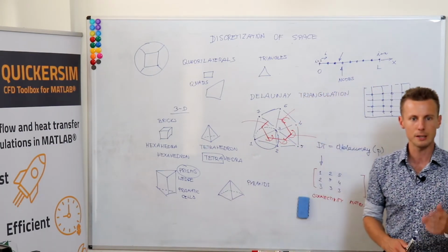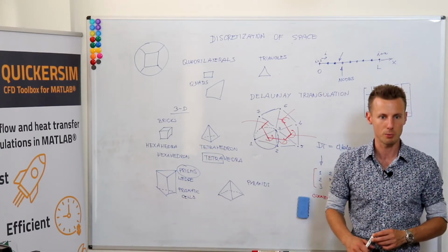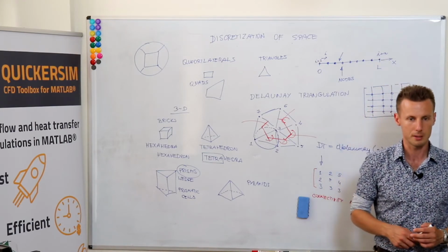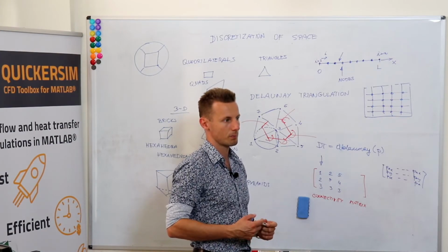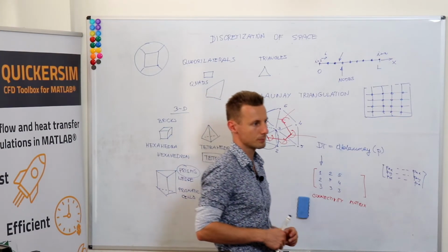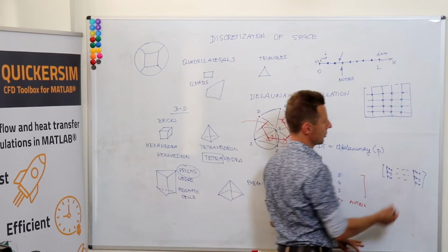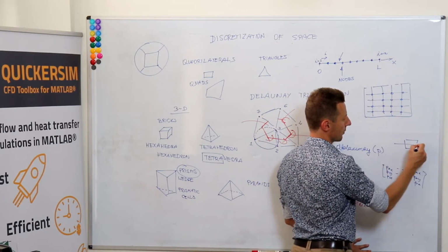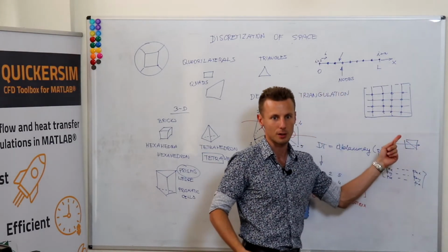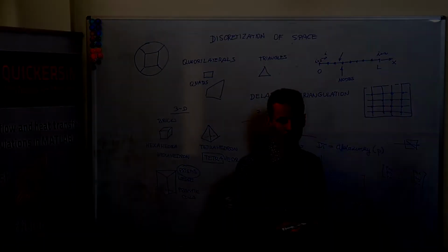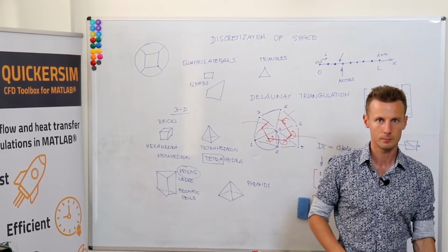But you already see advantages. Generating bricks for finite volume is nice. You end up with a smaller number of unknowns in the system. You can align the mesh in such a way that some walls are perpendicular to the flow and others are parallel to the flow, so you have small numerical values. If you generate triangles and you have flow like that, you always have fluxes that are skewed to the mesh. But you can always recombine tetras into polyhedrals.